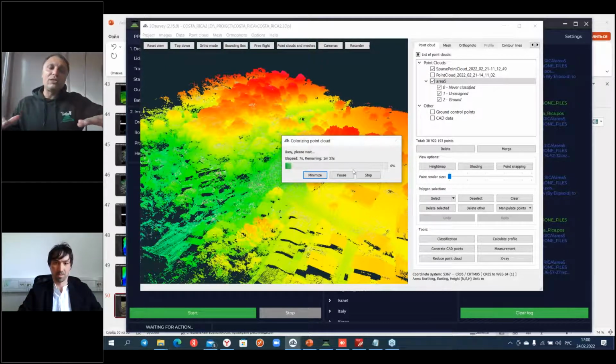As soon as our images are very precisely rectified because of the photogrammetric processing with precise coordinates of the images, all data processing is made totally automatically. What you need is just to click the button and nothing else, and the software will colorize the point cloud within a few minutes.